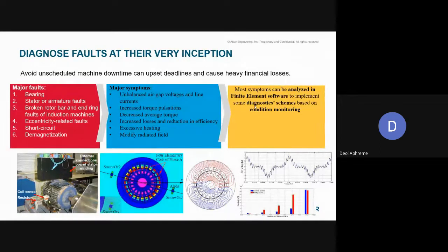So you might have one phase voltage shooting way over the other, simply because the air gap in that region is lesser. That is a definite possibility, and there can be structural failures, such as bearing failures or housing failures, armature and stator faults, in case your field winding is pushing too much current or voltage.